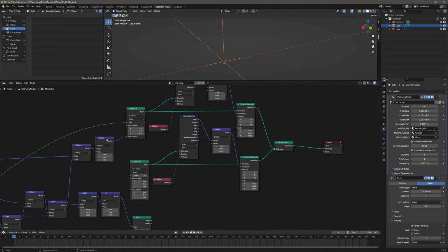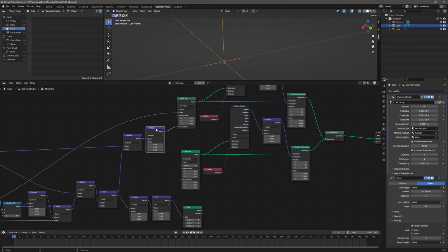Well, we haven't plugged the dimension of that line yet, so let's copy the multiply node, plug in the result of the subtraction into the vector, and this time I will zero out the x-axis and use only the y-axis. Now use that for the end location.